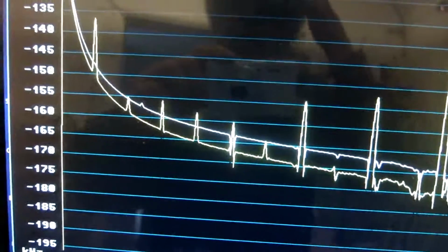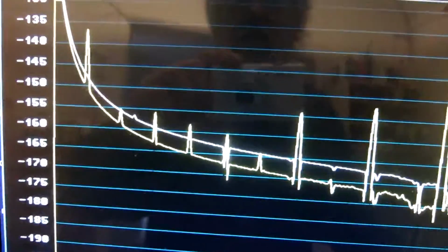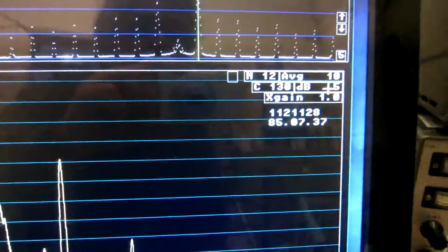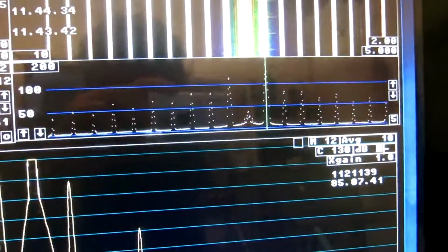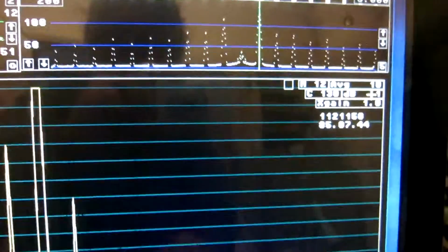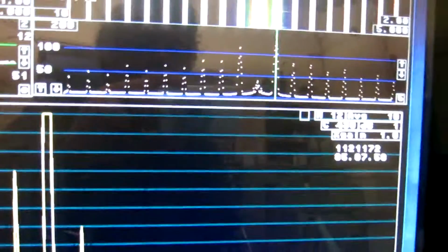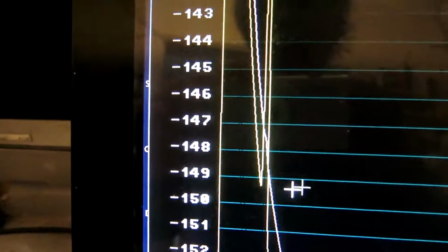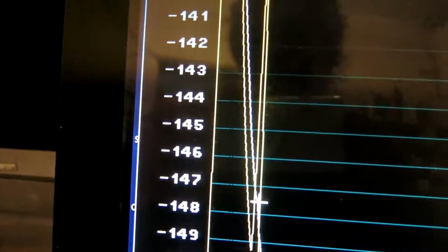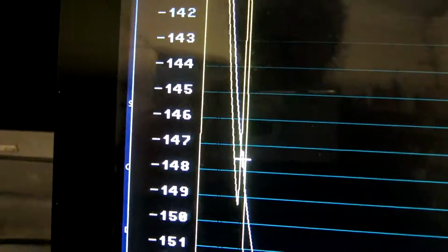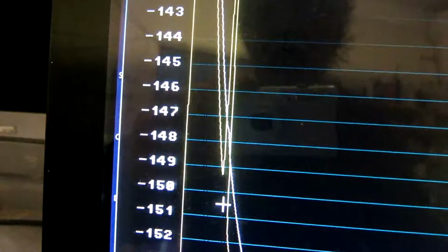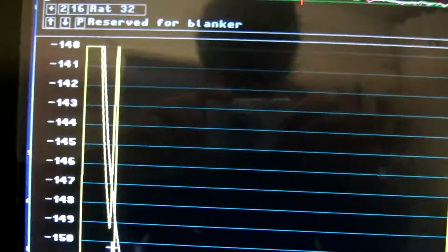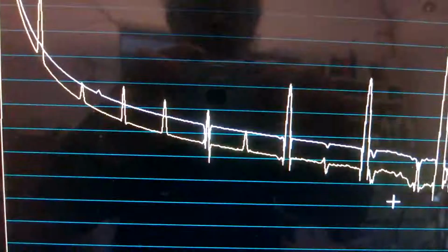I will take down the numbers for these curves, and I do that by changing the scale here, dB. I go from 5 to 1, and then I have to shift vertically the carrier position to, let's say, 140. And here I can read the value at 50 Hz. It's here for the amplitude noise, and at this point for the phase noise. And I will make a little table about the information I have here.